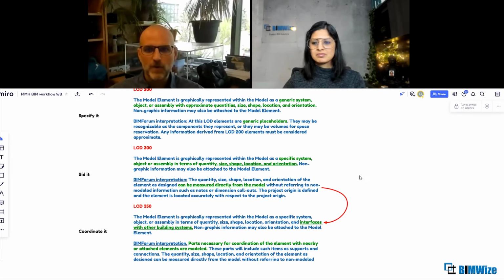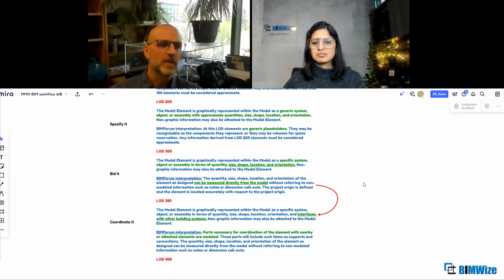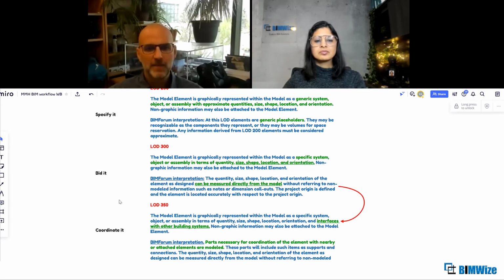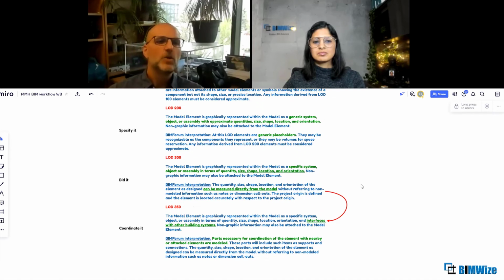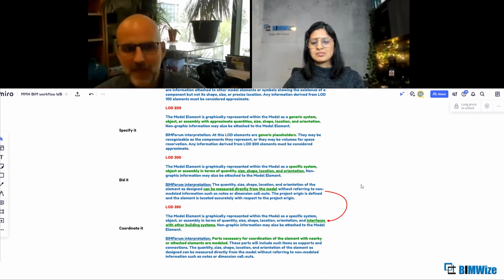The way we're using it right now is causing a huge amount of confusion for the clients we deal with, because they procure designers on the assumption that an LOD 300 model, taken from the standard that is out there, can be measured off the model and is coordinated. So a lot of times we get assumptions: well, you guys are going to get an LOD 300 model, and then all you have to do is build it. We try to explain, no, now we get trades on board and we redo everything, because if you want an as-built model, it has to be redone.